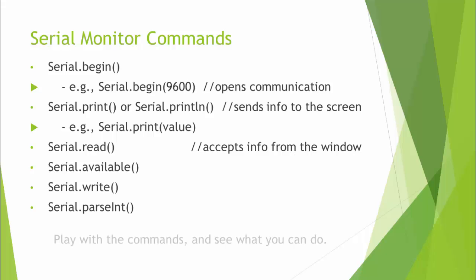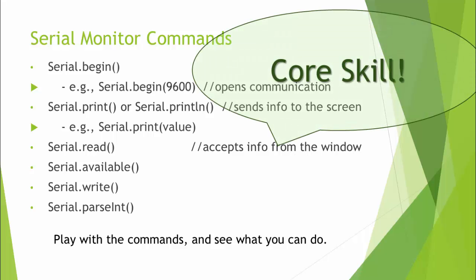They are absolutely critical to your success in developing Arduino applications. So mess around with them and see what you can do with it. But do not attempt to develop Arduino applications without understanding how to use the serial monitor. It is your number one tool for debugging applications.